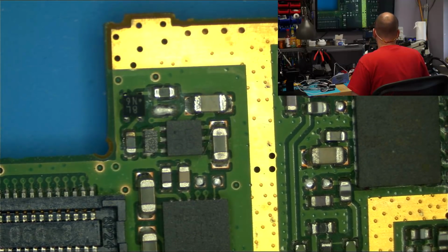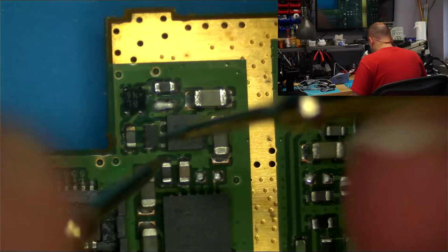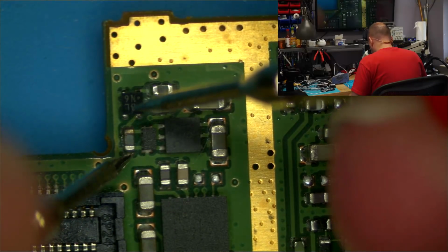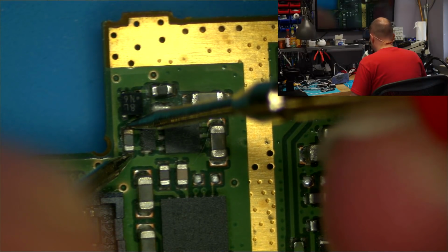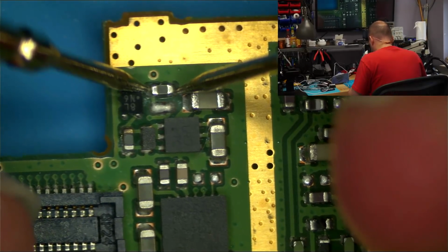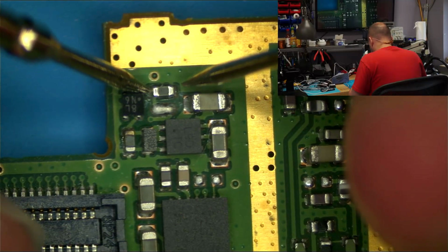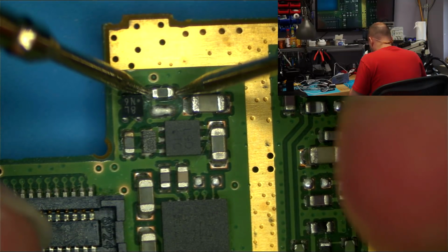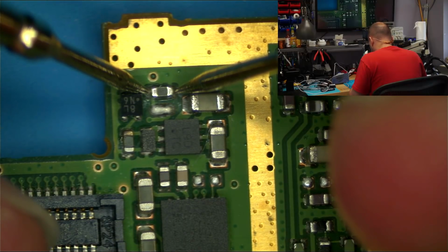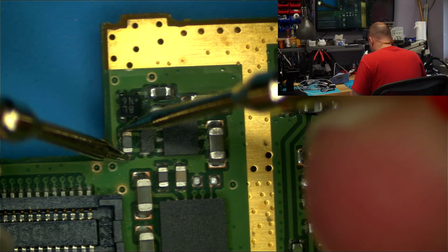Then maybe we could do a little bit of testing, though. Let's see if something's shorted. This could be a coil, by the color of it. Could be a capacitor. That is dead shorted. What is this one? Okay, that's supposed to be a capacitor, I guess. By the coloring, it might be a coil, but no. This one's open, so that's probably a capacitor. So this capacitor is a dead short.